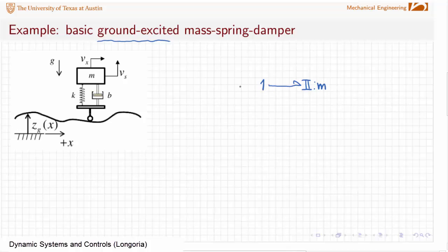And that mass also has, if we want to include the mass times gravity as a force here, and because that's acting down, we're going to put the power arrow away, meaning this is a force that's going to work against the increased momentum of the sprung mass in the vertical direction, right? Because our sign convention is positive up this way.